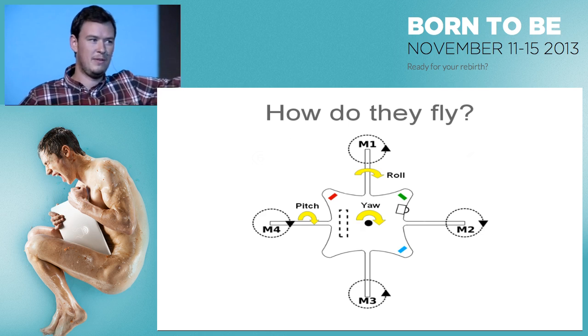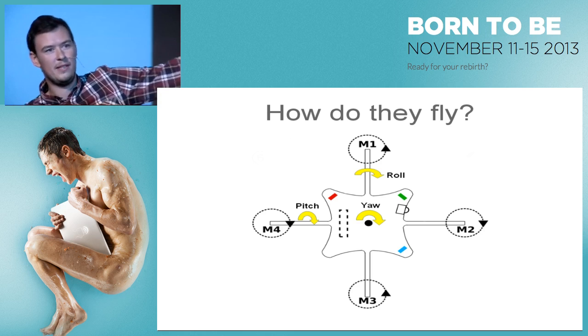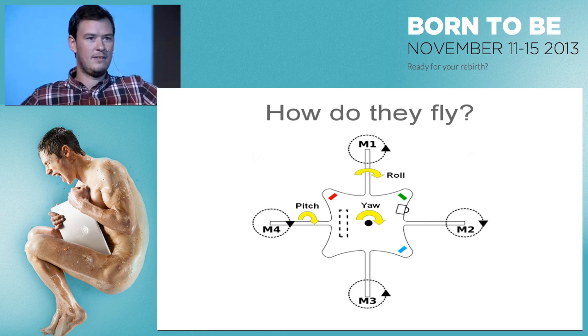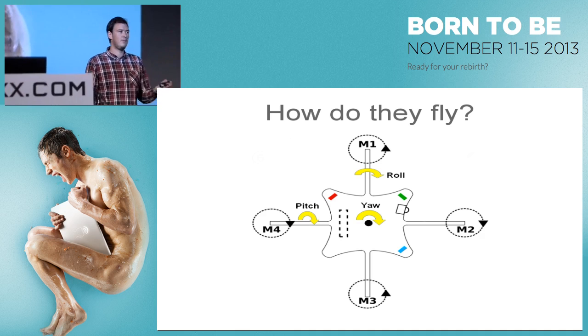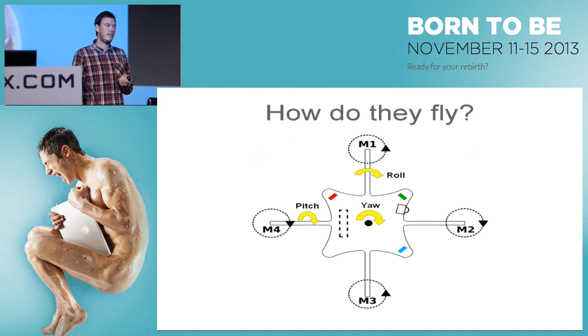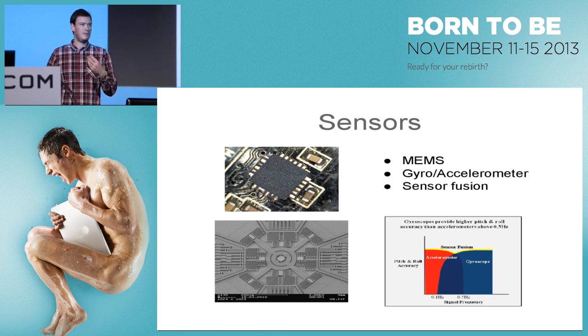By increasing the thrust on one side and decreasing it on the other, you will start to rotate. That you can do for these 2 axes, roll and pitch. For yaw, you need propellers rotating in different directions. So two of them rotate counterclockwise and the other two clockwise. By increasing the thrust on those, you will also start to rotate around your yaw axis.